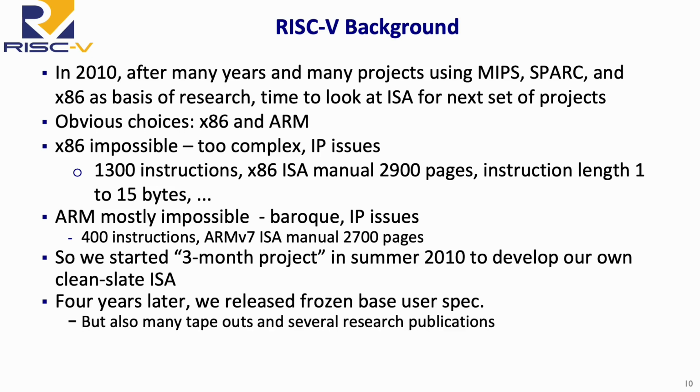And they'd started to see some people in industry taping out chips. And there were certainly lots of research publications. Although a lot of the tape outs, I have to say, are in devices where the person producing the chip controls both the hardware and the software. A good example of this is Western Digital, who do hard disks. What's critical there is if they find a minor bug in the hardware, then they can fix it in their own software. And so that de-risks things. Standardization efforts continue to go on for the privilege mode and other bits of the instruction set on RISC-V.